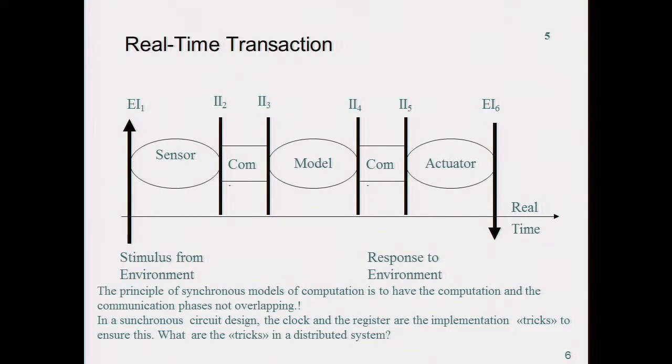So these phases, for an asynchronous model, like for example in automotive there is a CAN network, happen whenever, right? So a sensor puts up a data, and then everything starts: communication, computation, actuation. Another thing happens, it may be almost immediately after, everything starts, boom, boom, boom, boom. And then there is a chance that everything kind of collides, right?